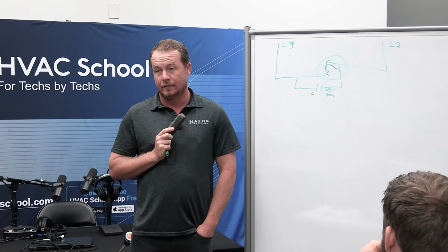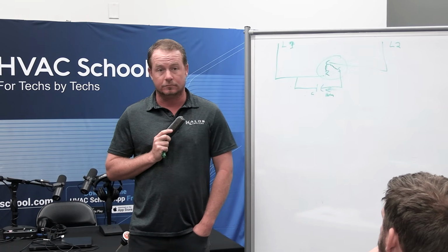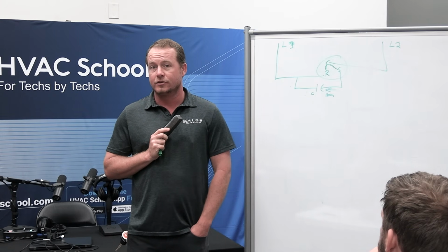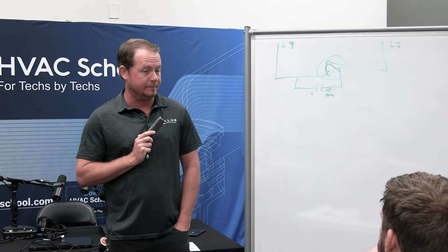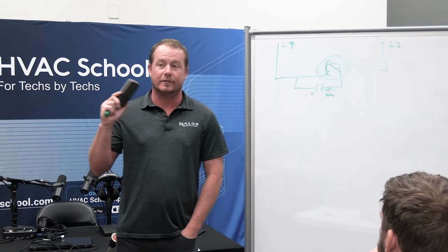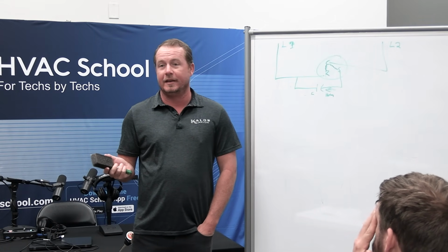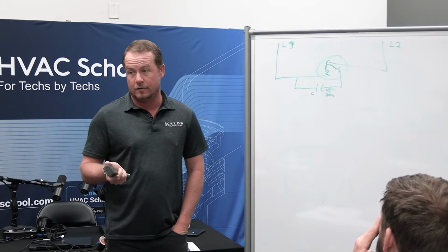It doesn't start. Might not start. It's not going to start smoothly at best, right? So what's going to occur inside that motor if you have a capacitor that's too small? You've got a baby trying to spin the Wheel of Fortune, a little baby hand trying to spin the Wheel of Fortune, right? So it's going to get hotter, right?